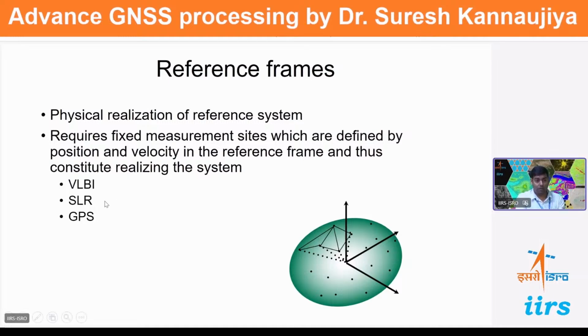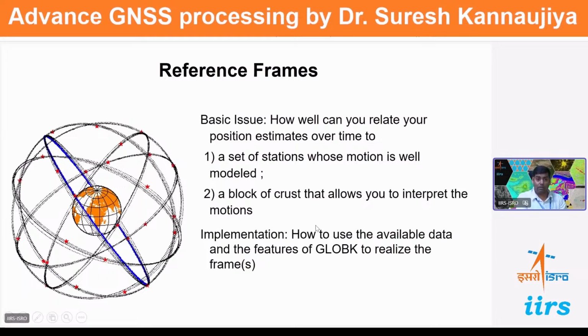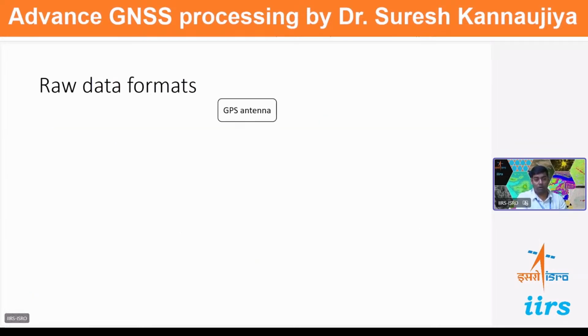Then there are different platforms and data providing this critical information, like VLBI, SLR, GPS. All these are providing information. When these are very accurate, then we are able to model it, and we can have very accurate data in WGS 84, ITRF, International Terrestrial Reference Frame, then the geocentric ellipsoidal model of the Earth. We are able to model a very accurate geoid through GRACE data. You know, the GRACE satellite, which is providing the gravity information globally.